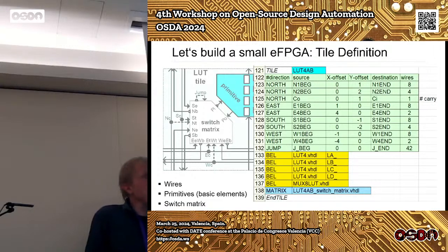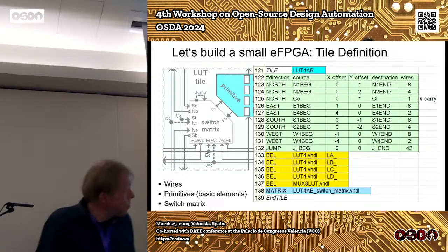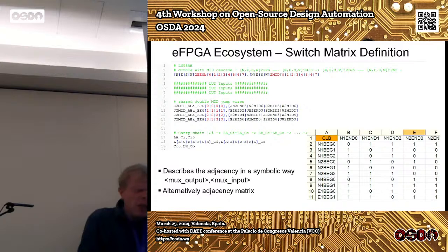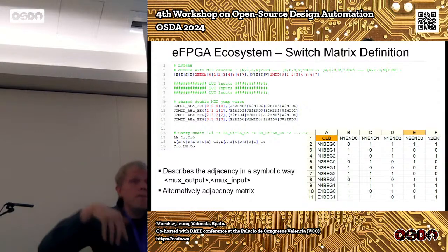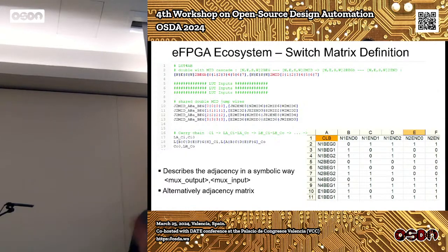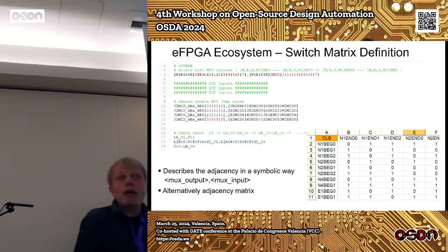You can just take our CLB, give it a different fabric, and inside your own accelerator, these bits stream in at the end. Let's start with all the outputs of the lookup table or of the switch matrix that are rows, and all the inputs that are here. In order to set a one, you switch on a point here, and you have your custom fabric with these things.